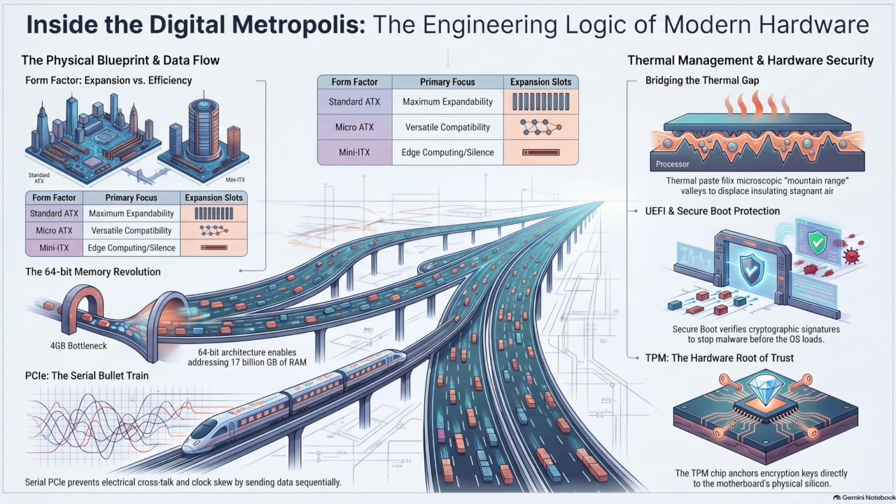Yes, and the syllabus highlights a massive historical shift here, from the legacy PCI standard to the modern PCI Express standard. This was a game changer for hardware. So the old PCI was a parallel connection. It would take a chunk of data, split it up, and send 32 or 64 bits simultaneously, side by side, down these parallel copper traces. All at the exact same time.